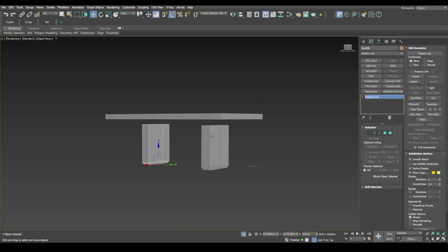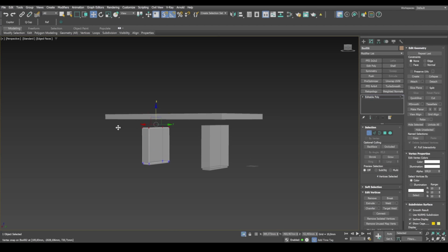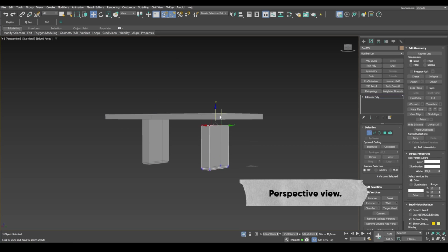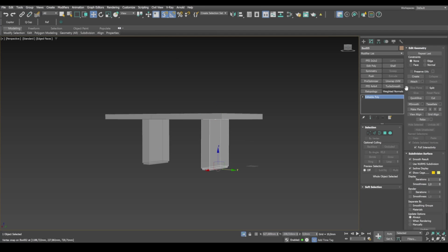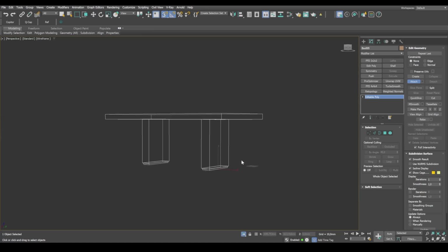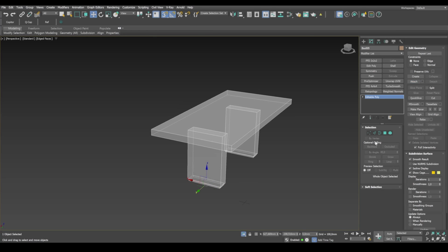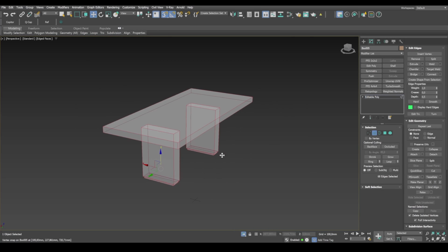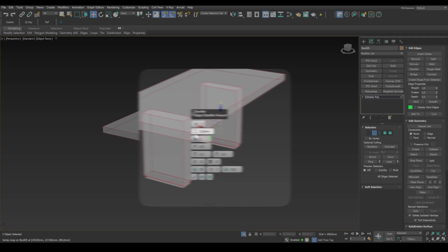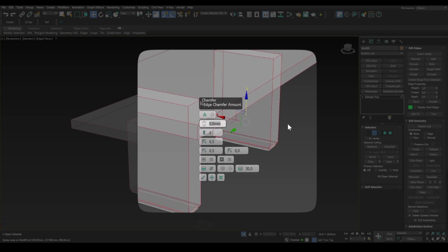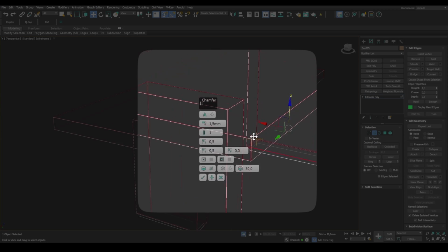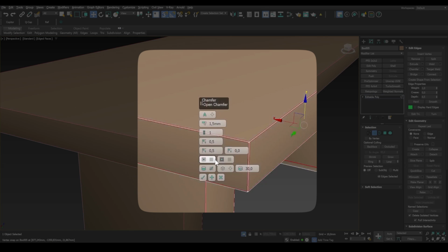And I can do this on the perspective view. Stretch the legs to the tabletop. Attach these elements to a solid object. Now I apply chamfer for all edges. For wooden tabletops, this value is around 1.5 millimeters, typically. This edge is rather rigid, so I'll reduce the smooth threshold value. Okay.